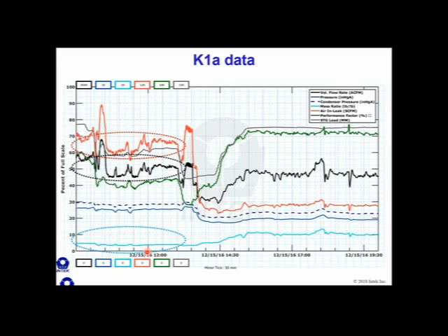It's a very nice parameter. So we'll talk about why that is in a couple of slides. But here's the air in-leakage at 70 SCFM. They're running along. This is their volumetric flow rate at about 1500 CFM, which is a decent flow rate for their two small TC7 vacuum pumps.